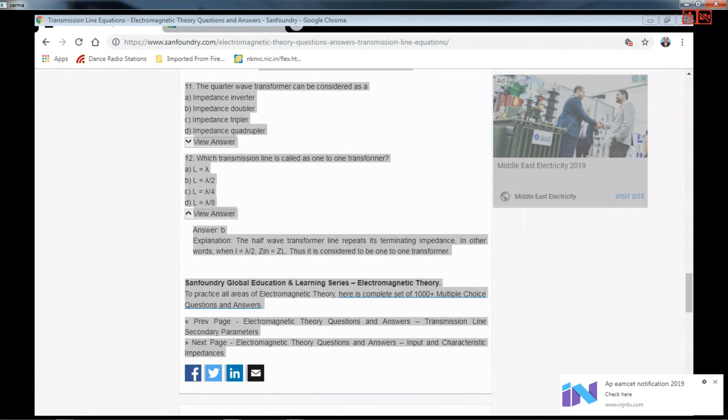So the reflection coefficient, as you move from the load on a transmission line not having any attenuation, is going to vary in terms of beta. If theta gamma is the phase of the reflection coefficient at the load, and at a distance of z prime the voltage minimum is going to occur, then by moving the reflection coefficient from the load up to this point of minimum, you will be adding a phase of 2 beta z prime.